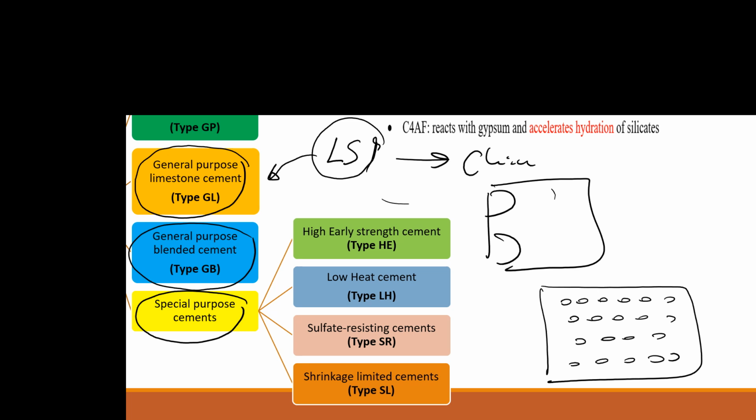Water passing through. Yes, so whenever you want to make a porous concrete, you have to. But there are some issues with other situations. For example, if you have a sulfur affected area, I told you the concrete is getting swollen. So we need to provide the space for the concrete to expand, otherwise it will crack, isn't it? So in that case, we have to have an air entrained concrete. Again, if our concrete is in the freezing environment, we need to have air entrained concrete.